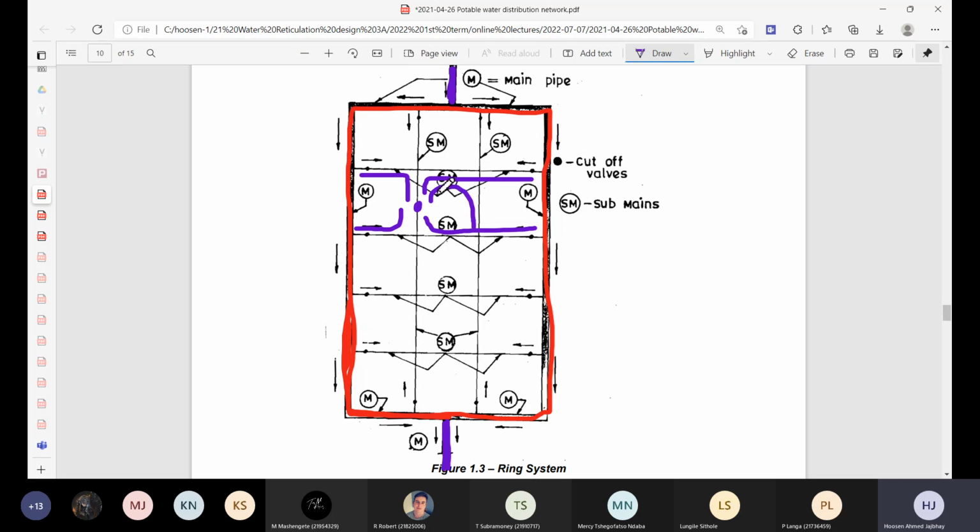So you might have, for example, the longer route. That would obviously have more friction losses because you have a longer pipeline. So the pressure head may be lower coming teeing off from the direction that I'm showing you now, how my cursor is going, as compared to from the left-hand side, where it's a much shorter route for the water to come to that point. So you have lesser frictional losses, so you could have a higher residual head at that particular point. Right, so the main advantage is you have a much better pressure distribution and higher residual pressures at any particular point in the network.